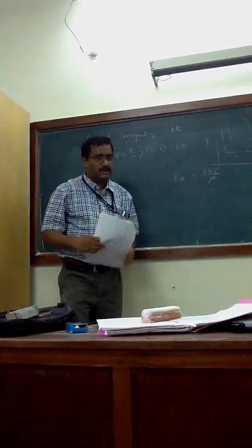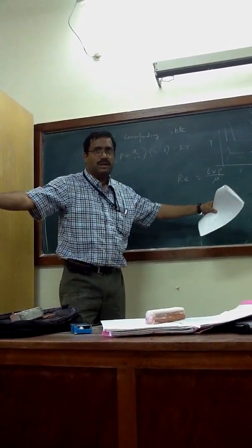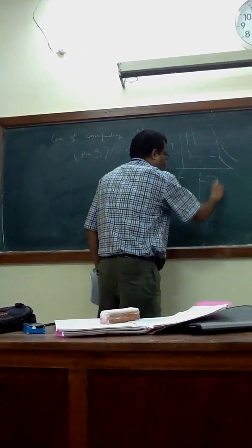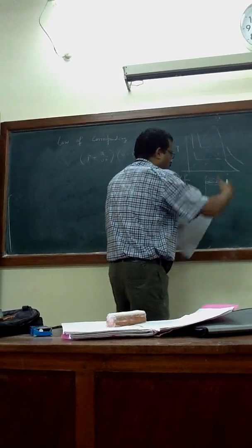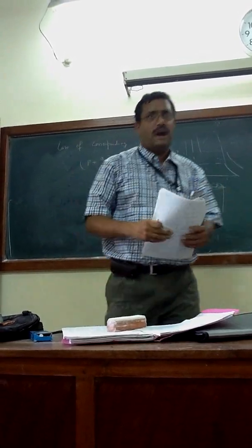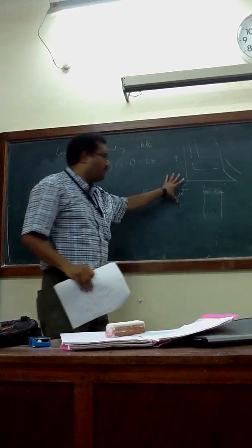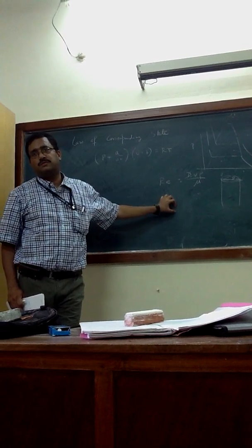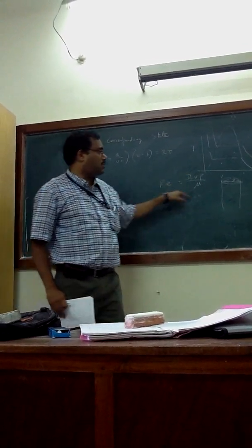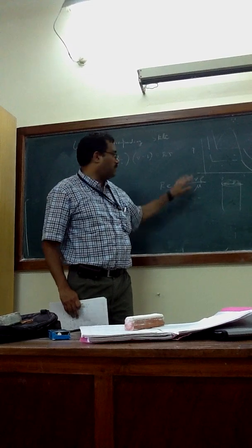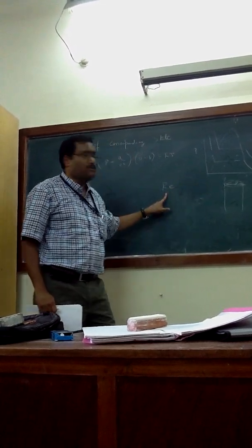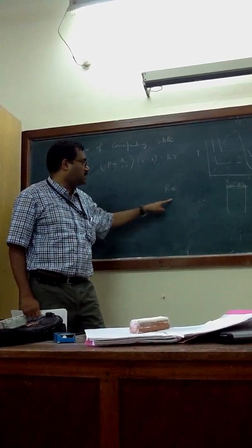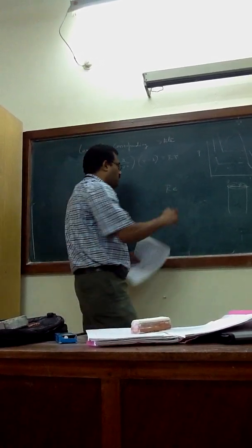Whatever the channel, sometimes I have a big channel. This is actually d V rho by mu, which talks of the cross section, diameter. So I have a big diameter, I have a small diameter, I have petrol, I have water, whatever the case, everything is included there. This number is a parameter. This number says that the flow is laminar or turbulent, depending on all this material property. But if I don't know the material property, I know only this number for Reynolds number. This does not take any material, it is invariant. It is a material invariant.